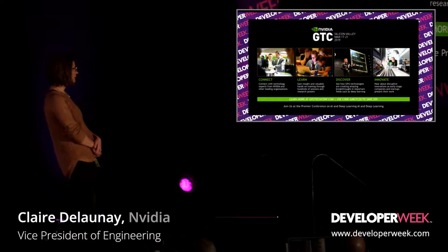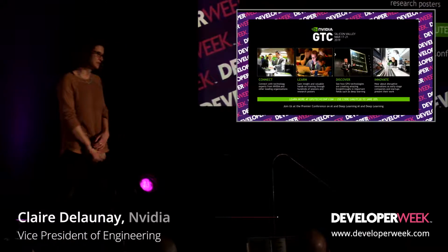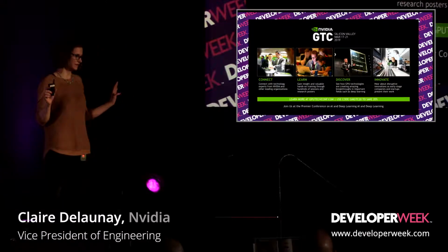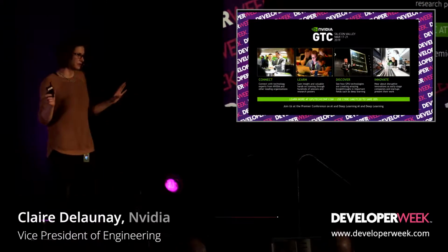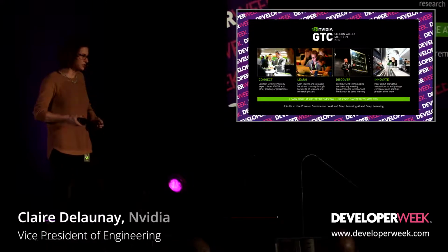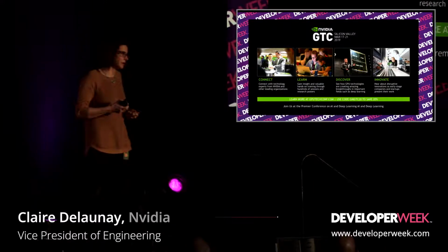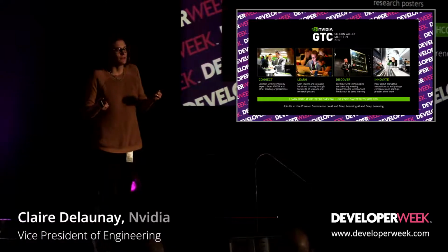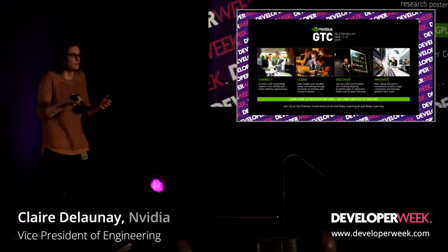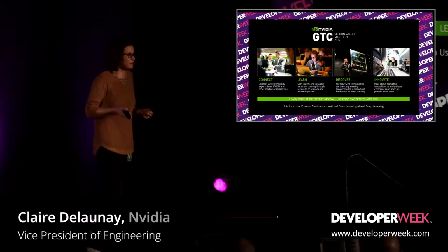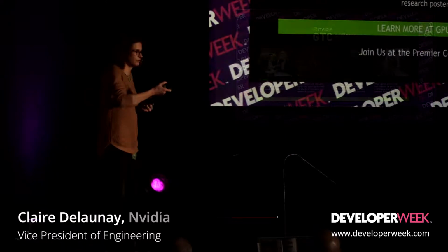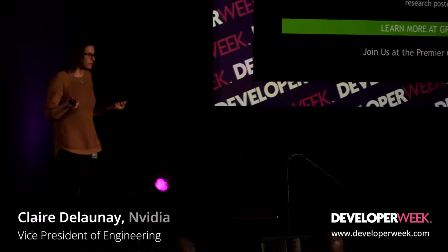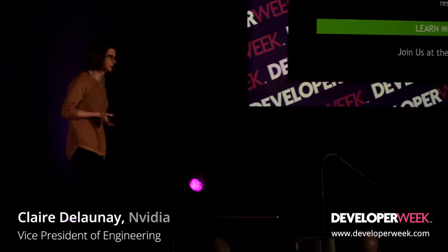So I think the diagram actually was not very accurate. I would see more ROS side by side with Isaac. We have a very similar component-based architecture. So we have wrappers, and you just write wrappers. The main thing you need to do if you want to couple a ROS system with Isaac is basically make sure that the serialization you use is converting the message into the right format, because we have another serialization protocol. But otherwise, it's very similar.